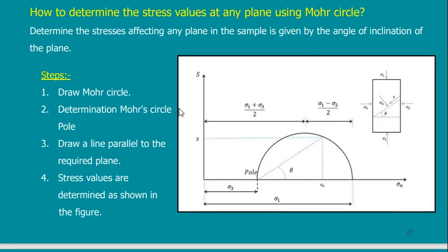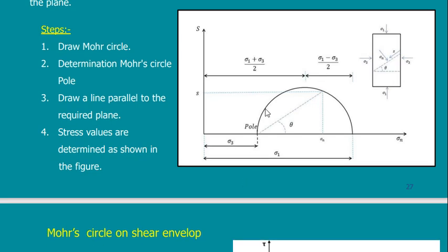But what is important for us is this drawing. This is the Mohr circle. If I have a sample subjected to sigma 1 and sigma 3, I go to this drawing, I put here the value of sigma 1, I put here the value of sigma 3, I consider this the diameter of a circle, draw the circle, and using this circle, I can give you the normal and shear stresses at any inclined surface. How? Just draw the inclined surface, measure the angle, take this angle, draw it here, cut the surface at any point, and you will get the normal and shearing stresses at any point.